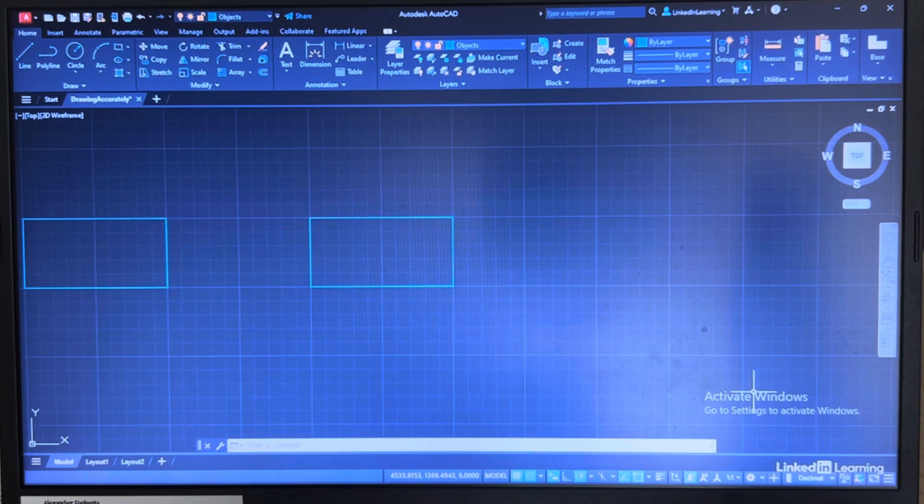Now we're going to start using a lot of the drafting settings all at once in AutoCAD. And this is basically how I draft everything now. You know, back in the day we didn't have all these settings, but they make your life so much easier, these drafting settings. Now, the reason I switched the snap on here is like with this rectangle here, we just want to be able to snap to the grid quickly.